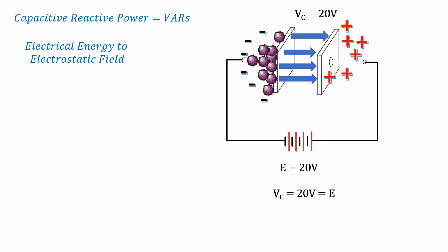This creates an electrostatic field where the electrons want to get to the positive ions to balance out the system, but they can't because of the dielectric separating the plates. This creates a static field where there is the force of attraction, but it cannot flow. So now we have potential energy between these two plates. So we've stored an electrostatic field or potential energy on our capacitor.